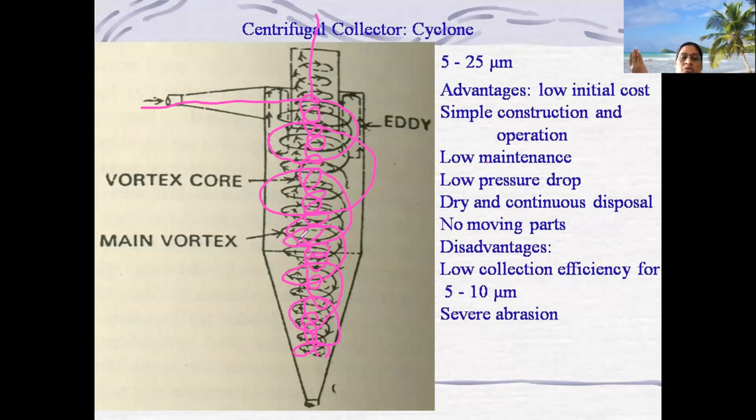The tendency of the gas is to go up. That phenomenon starts working once the pressure applied on the gas at the inlet gets released. From that, it starts creating the inner vortex in this chamber, and at the center or top of this cyclone separator, the gas exits.